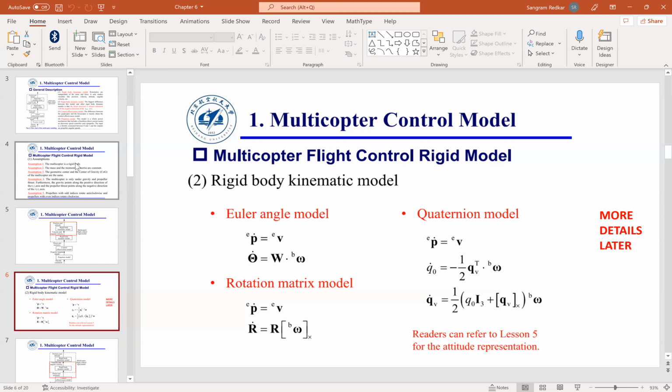So I want you to visualize that this is a UAV. Initially, the UAV is in simple hover. So in this particular case, you agree with me, my Earth-centered, Earth-fixed coordinate frame and the UAV coordinate frame are aligned. In that particular case, only at that instant, this is very important, only at that instant, the roll rate, pitch rate, and yaw rate align with the inertial rates. Once again, I repeat, this is the UAV. Let's identify the coordinate system. So this is north, east, down: north, x; east, y; down, z. You agree with me? This is the coordinate frame. This is my Earth-centered, Earth-fixed coordinate frame that is fixed to Earth.